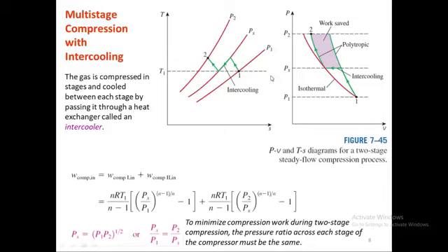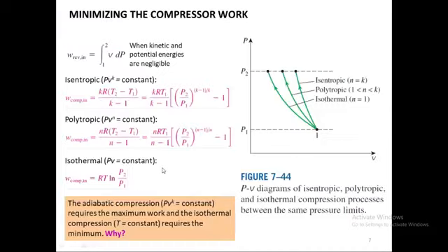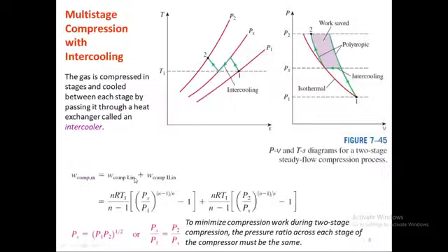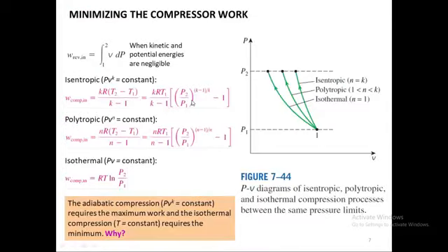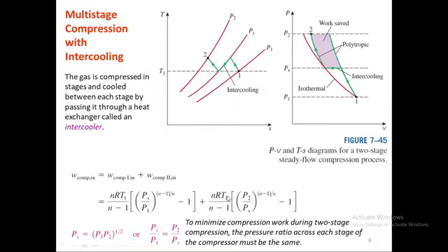How to achieve this, how to find out the middle pressure? For that we have added the compressor work in compressor 1 plus compressor 2 work together. So these are the isentropic equations for the two, or rather the polytropic ones. The polytropic equation will follow, and then we find the minimum.